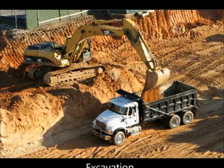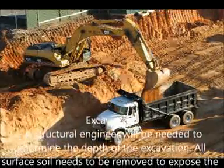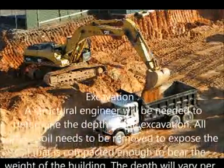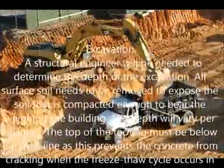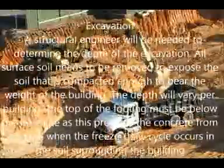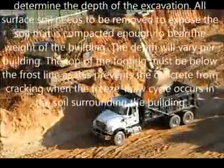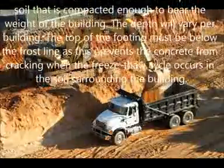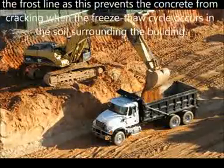Excavation. A structural engineer will be needed to determine the depth of the excavation. All surface soil needs to be removed to expose the soil that is compacted enough to bear the weight of the building. The depth will vary per building. The top of the footing must be below the frost line, as this prevents the concrete from cracking when the freeze-thaw cycle occurs in the soil surrounding the building.